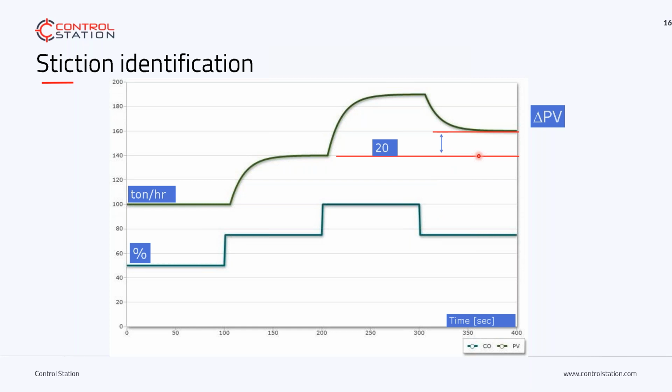Again, with process control and PID accuracy, repeatability is key. If it's not there, question it. And the likelihood is it's stiction, that the valve has not come back. If you stepped down again, you're probably going to recover this value here. But it's useful as two methods of measuring stiction. You could do this with a set point. If you step the set point up a couple of times and then step it back down to your normal operating point, if it doesn't stabilize, it is going to attempt to recover, but you will see this lack of match between those, and that is what will happen.